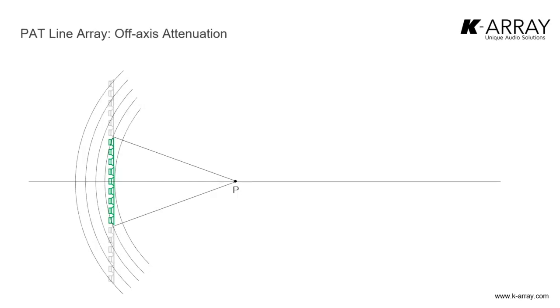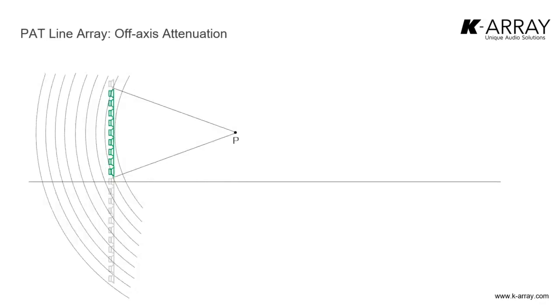If we go back to our picture where we have our microphone, and we already said that only a few woofers in front of the microphone effectively contribute to the energy at that location, what happens if I move off axis? Well, here I'm still, let's say, inside the column, and I'm still in front of the same amount of woofers, so I'm not expecting a big SPL variation from here to here.